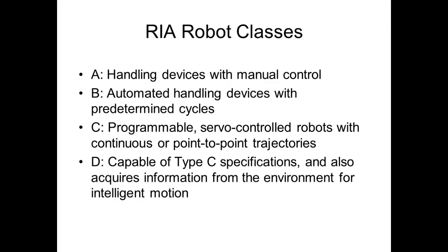You have a sensor that indicates the speed of the car. And if the car is going too slow, what does it do? Speeds it up. If it's going too fast, it automatically slows it down. That's what we call a servo system. Also called a closed loop. So those terms are used interchangeably. So closed loop and servo means these are systems that provide feedback indicating that they do what you tell them to do.